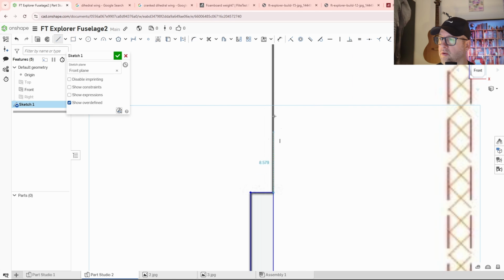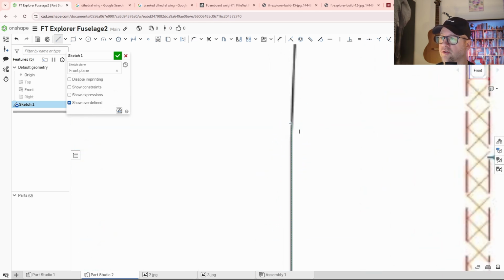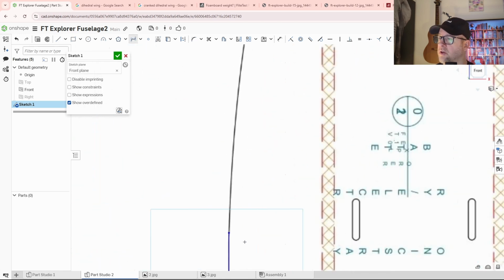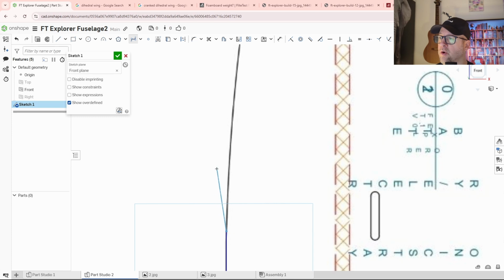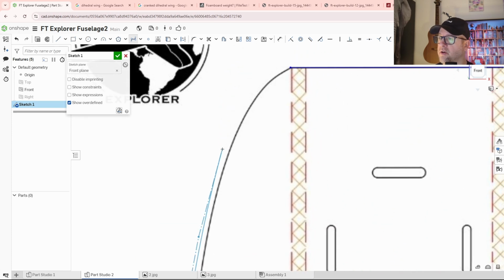L. It's continuing on, so that's good. Alright, when I start seeing the transition, that's where I'll stop it. Right click, escape, and now I gotta do a Bezier curve. So to do this Bezier, we go outside. Just gonna choose it all the way around, and then we start getting closer to it, and then snap it there. Right click, escape the Bezier.